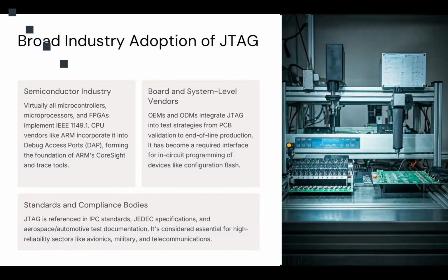It allows boundary scan testing to be performed at the system level. So it also tests the interconnection between all the chips and microprocessors, besides the internal inspection that it does in each individual IC device.